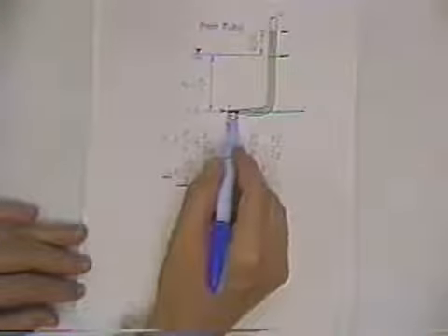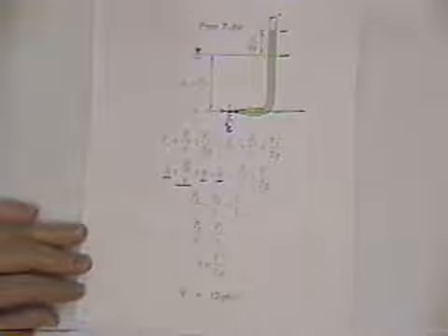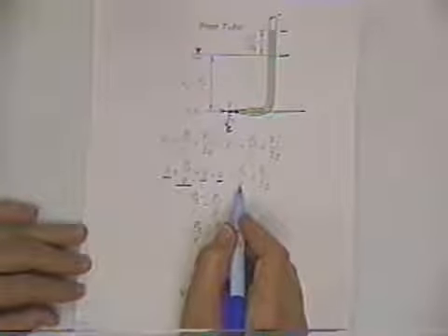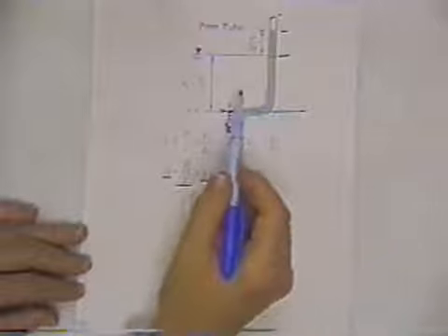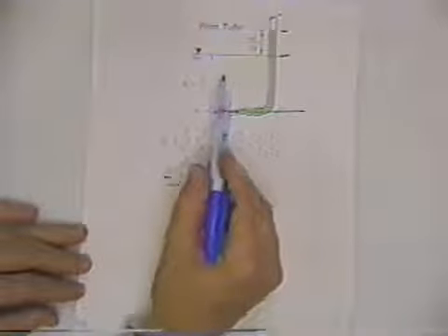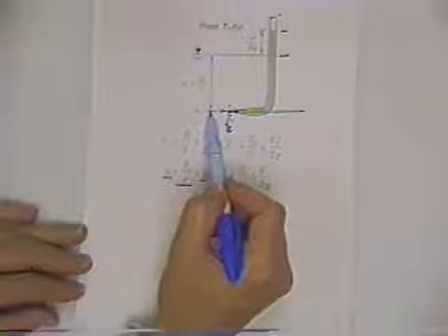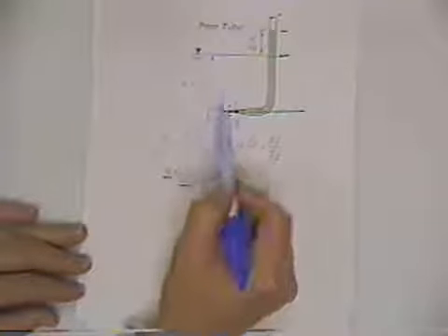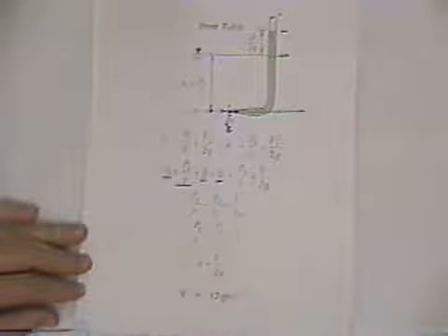Now, if you're outside the entrance to the tube, and say we're at the same vertical elevation, so our Z is still 0, and we've got some pressure, and this is the pressure head. You know, if you're outside the tube, the pressure head from fluid statics, no different than from fluid statics, is just the pressure would be the gamma times the vertical difference in elevation between the water surface down to this point of interest to us, out here in front of the pitot tube.